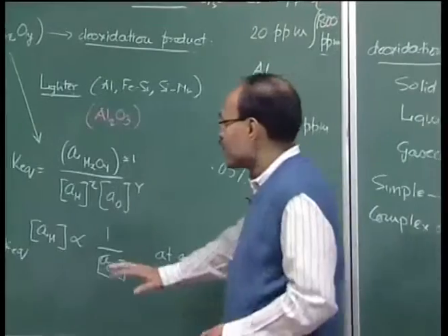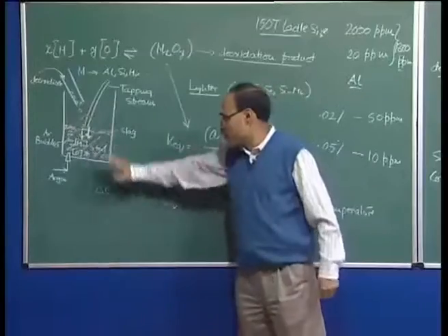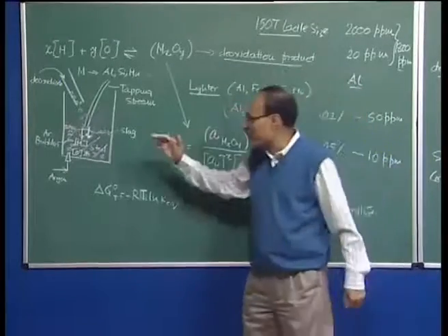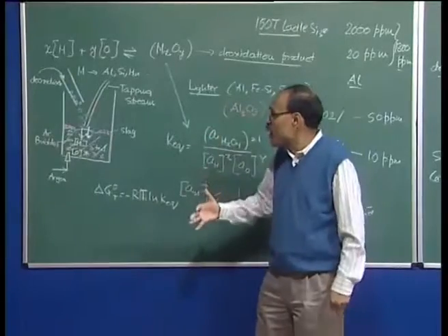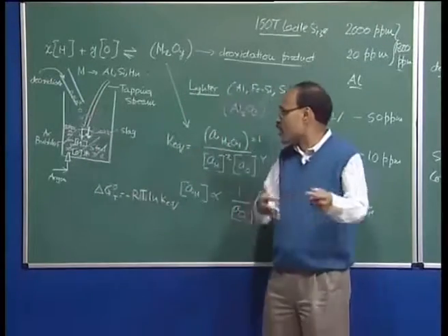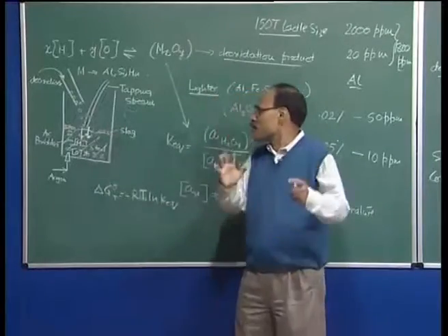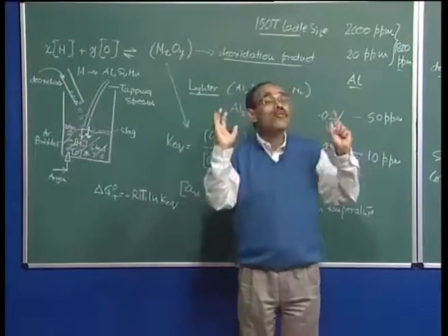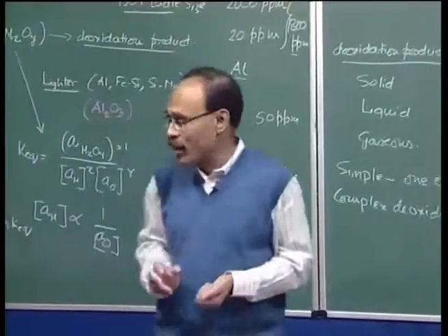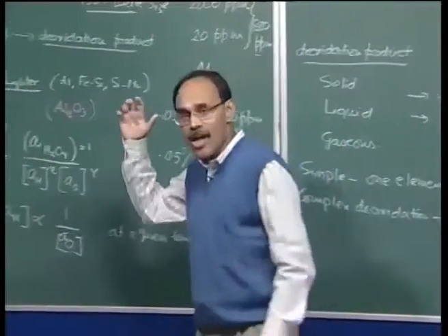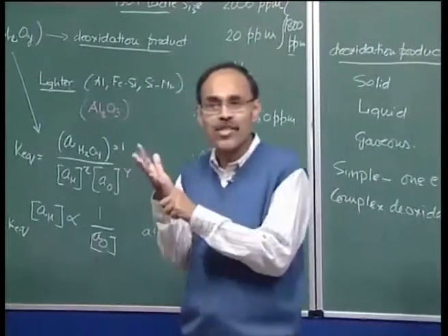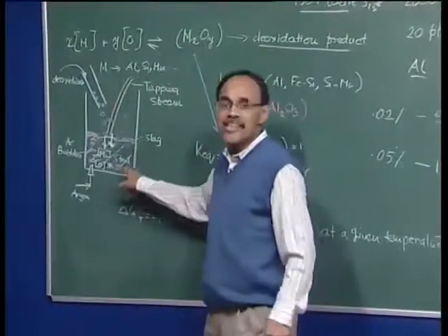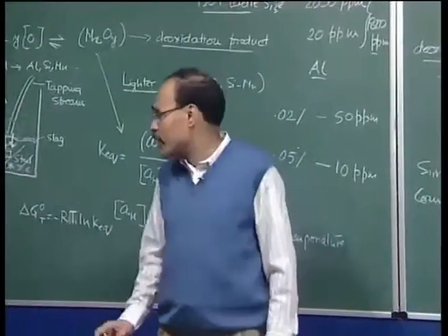It is important for us that the molten steel is free of such deoxidation products. In secondary steel making or ladle metallurgy, as we will see, as the processes go on and we generate more and more deoxidation products as a function of time, one of our major thrusts would be, if there are inclusion particles present in the melt, how to drive them out, how to produce clean steel, which is a very important, pertinent issue. Okay, we do not want dissolved impurities, we do not want much sulfur, we do not want oxygen. Okay, we do not want nitrogen, we do not want hydrogen. At the same time, we do not want unwanted non-metallic inclusions in the steel bath itself.